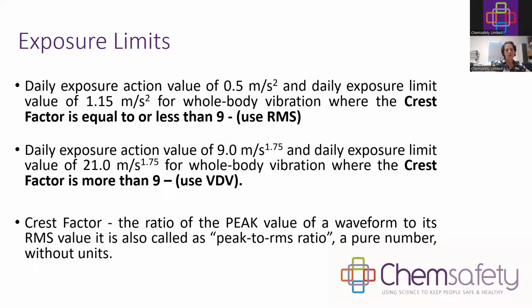And then when your crest factor is more than 9, you'll use your VDV, and your VDV will be used to see if your daily exposure action value is 9.0 meters per second to the power 1.75. And then also your total whole body vibration limit of 21. Sorry, I'm just quickly checking one of my notes. So what is meant with the VDV is the vibration dose value.